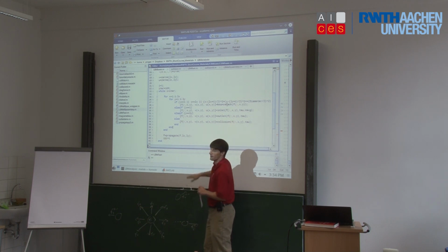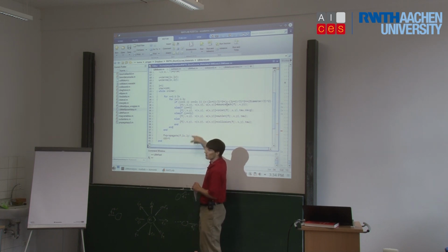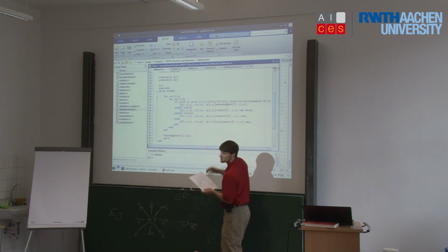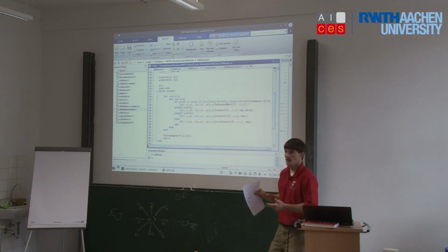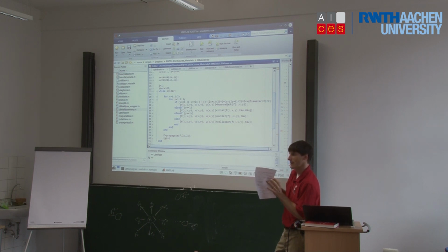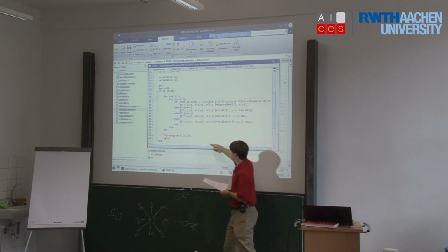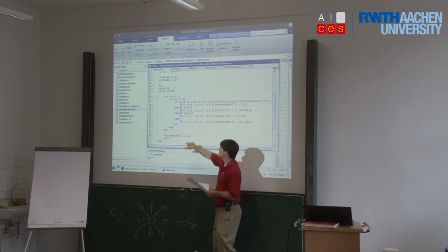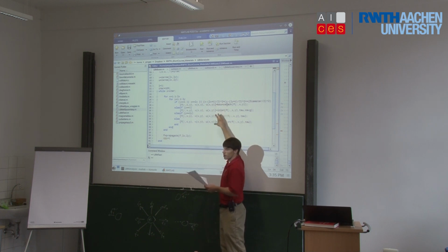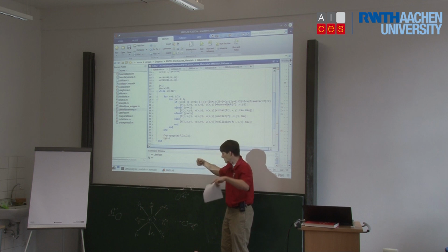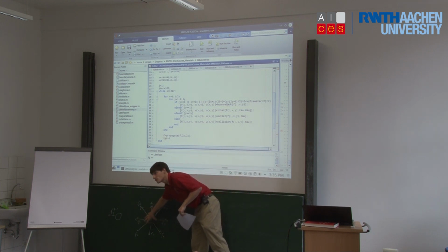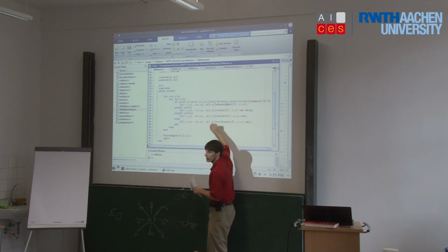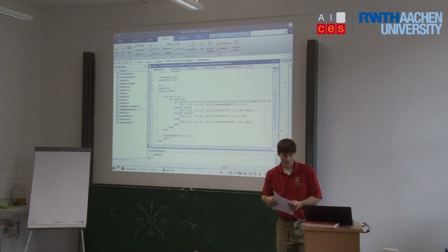Will they not use the f values from the neighbors? No, that happens only in the propagation step. Oh, okay. So only the collision step and the inlet, outlet, and bounce back are entirely local. Okay. I thought it was a little bit less local. No, it's entirely local. It's completely local. And then the propagation step is the only place where you now move stuff to the neighbors, and then you go back to the next collision step, and so now the neighboring nodes collide. The new information has moved to this point, and those new 9 values will collide again, and you kind of repeat the step. Okay, fine. Thank you. Yes.